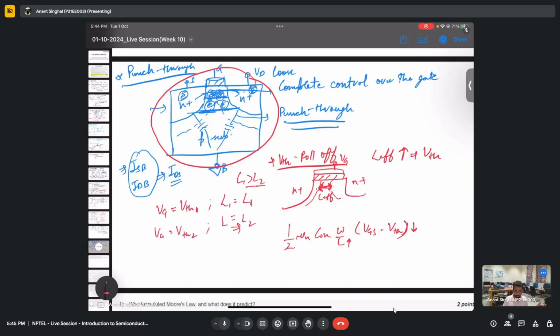This is a very basic understanding. Because we will have a lesser effective channel length, we will require a lesser threshold voltage. Threshold voltage depends upon the flat band, but flat band is not coming into the picture. We will have Q depletion by Cox, and finally the surface potential. So this surface potential is the thing that is coming into the picture. We will effectively require a lesser surface potential if we have a lesser effective length.